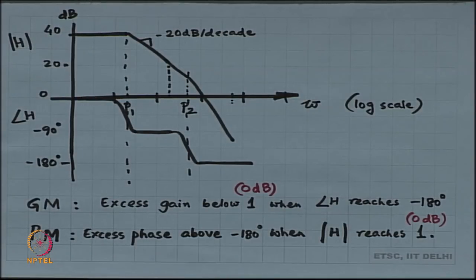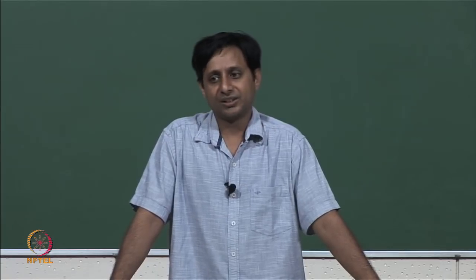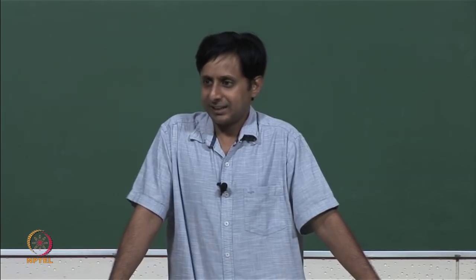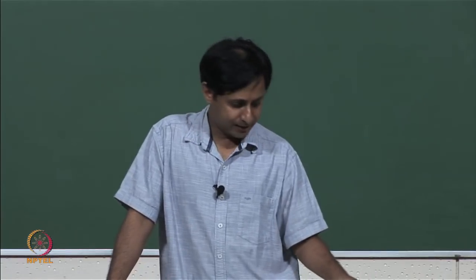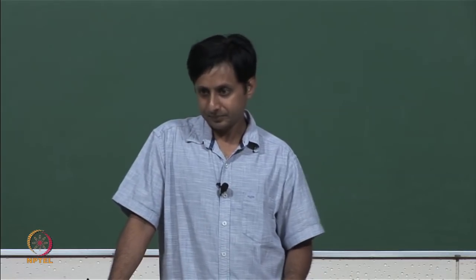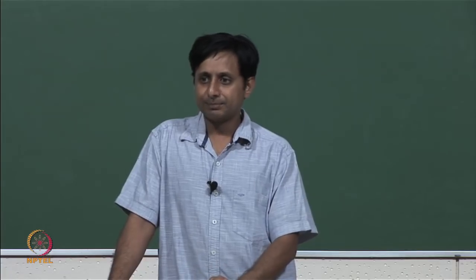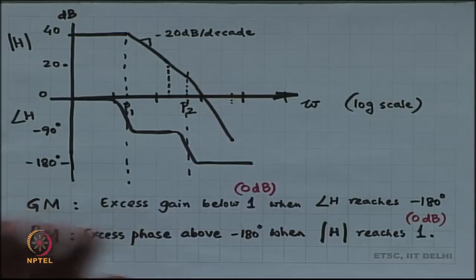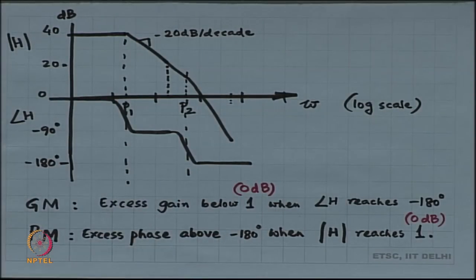If you have got positive gain margin, positive phase margin, then the system is going to be stable when you place it in unity gain negative feedback. All right. So, this is the theory, this is coming from your control engineering. We are not going to try to prove it, that is not our business over here. I am just going to state this.